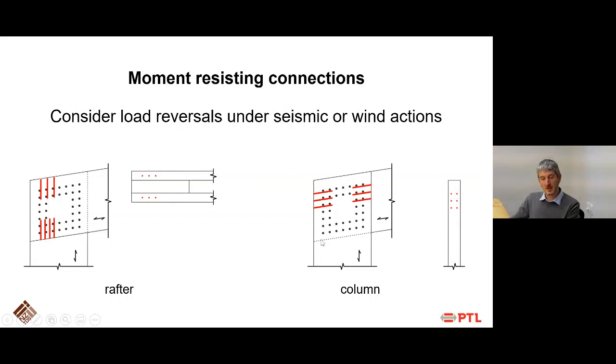You normally don't have to reinforce the lower part of your connection because it is further away from the end grain and has sufficient capacity to resist the tensile perpendicular to grain forces. Again, this is something you really need to check if you rely on the ductile behavior of your connection, and I recommend you always apply reinforcing for that.